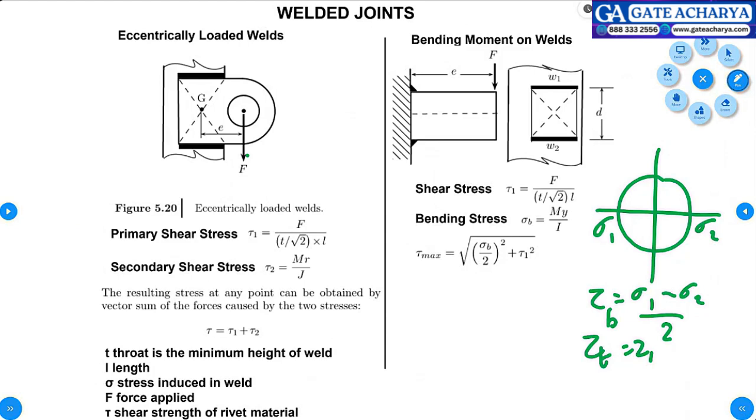Why are we doing this? Do you understand? These final expressions always come from the Mohr circle, where we plot sigma 1 and sigma 2 along the y-axis and x-axis and get the values of shear. So do you understand the difference between these two?